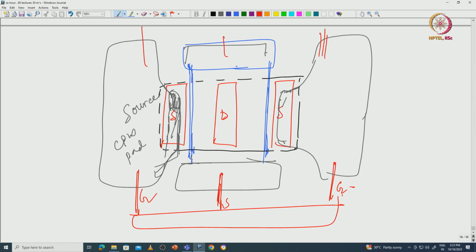Why this elaborate arrangement? Because RF are electromagnetic waves. So, there will be an incident wave, there will be a reflected wave, and then there will be a transmitted wave. You cannot escape this description. Because of the way the electromagnetic waves or the RF waves behave, you need this coplanar waveguide to measure on-wafer devices.